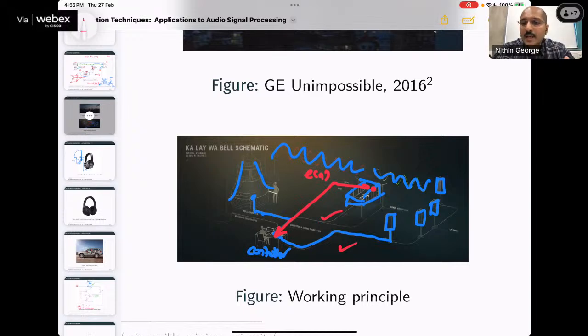Yeah, so that's why all our algorithms are adaptive, because I am continuously monitoring what is the environment noise, what type of noise. It is not like you have a fixed anti-noise signal generation, because your input signal will keep on changing, your head will move. Understood? When you are wearing a headphone, all of those things are going to move, but even then the algorithm should work because it is adaptive. The algorithm is always running, it is not that once you did it, it's all over. It is always looking for better and better solutions.